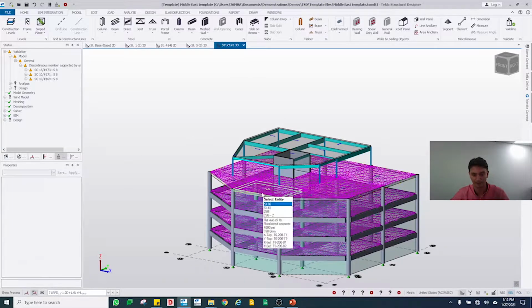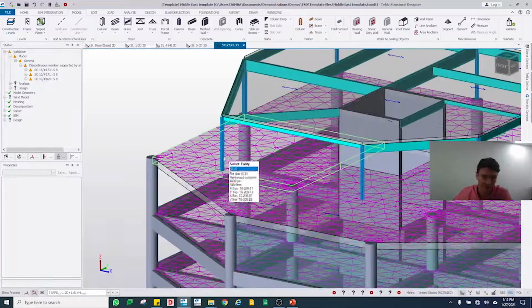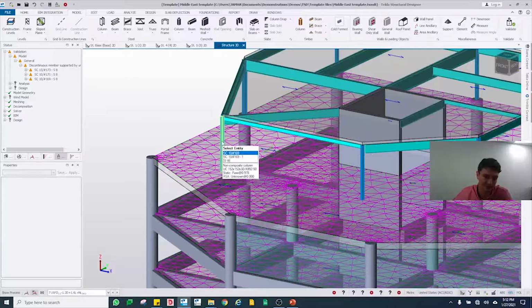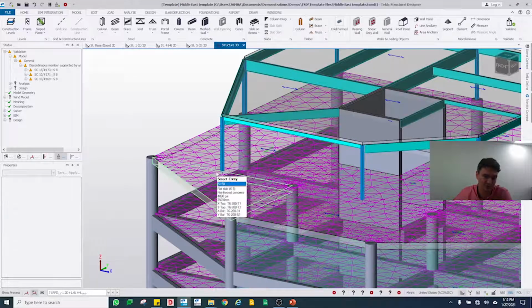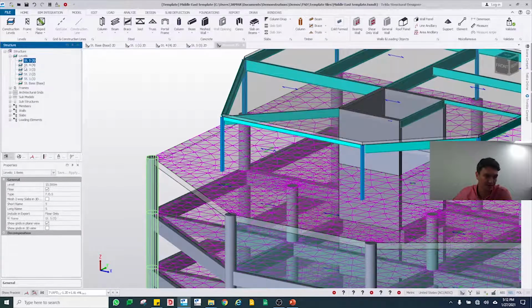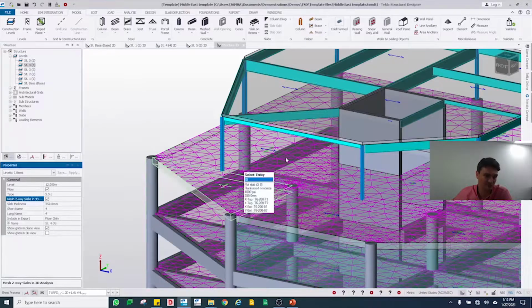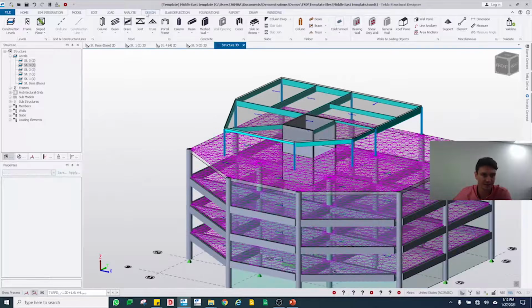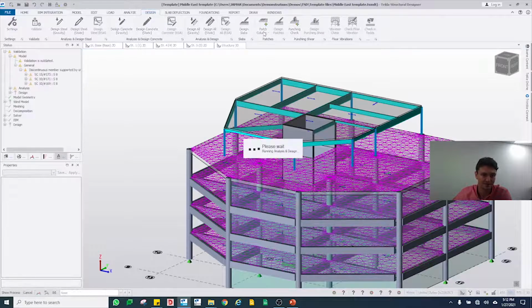So yeah, with a flat slab here, because of the way this slab is meshed, there's nowhere currently for the force from this column to decompose into this slab. So what I need to do is, at level 4, mesh two-way slabs in 3D. Now when I rerun the design, it should redesign and reapportion that loading to the slab, which then gets decomposed.